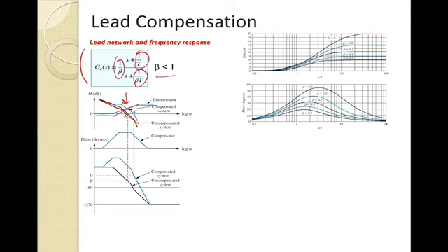Okay, and so the compensator again starts up here to a finite point, and then maybe comes down here as we look forward in our system. And that's a phase. This was magnitude. I didn't call that out specifically, but that lower one is going to be the phase of the compensator, and then you'll see the compensated phase on the last plot down here below. So you'll see that result here.